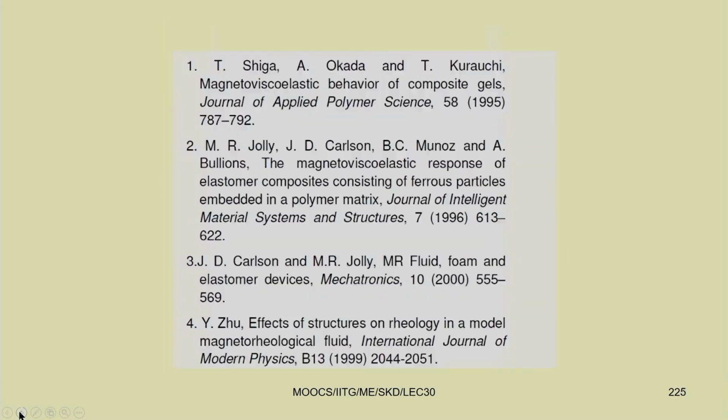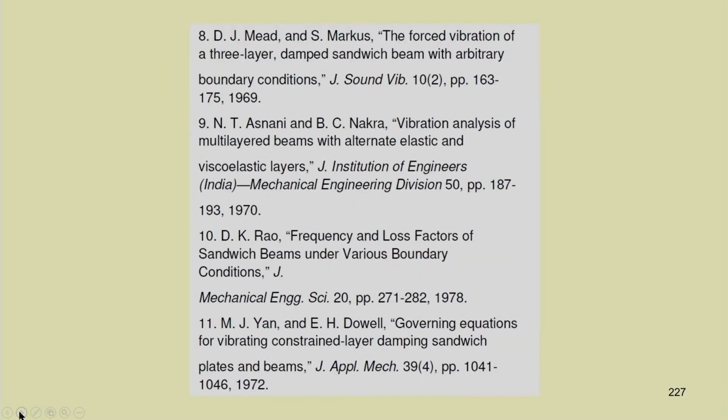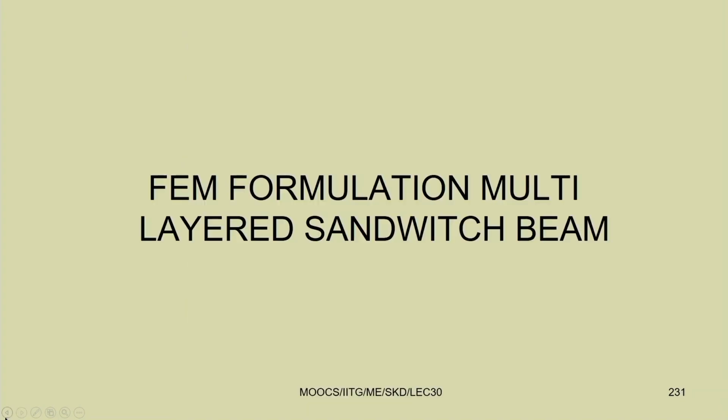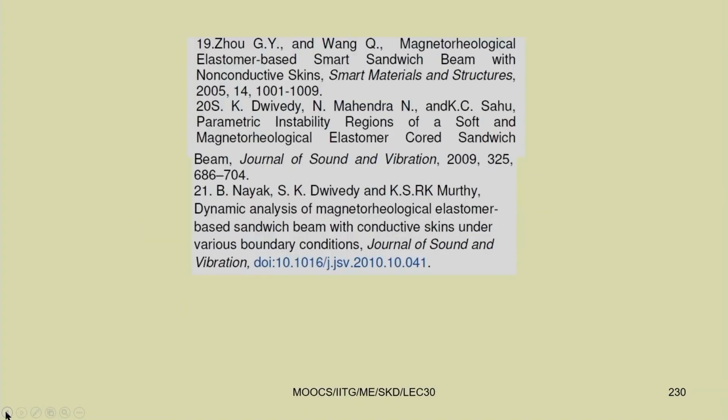These are some of the references you can see. So, let us conclude this session here. Now, you know how you can use a continuous system for analyzing it as a nonlinear system. You can reduce that spatio-temporal system to its temporal form by applying the Galerkin procedure.